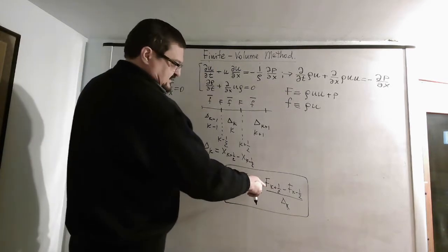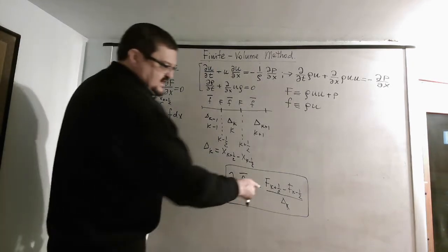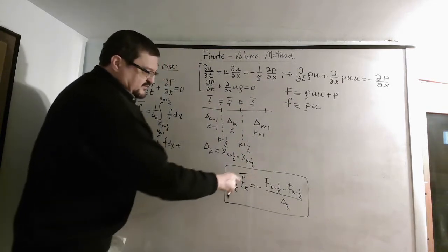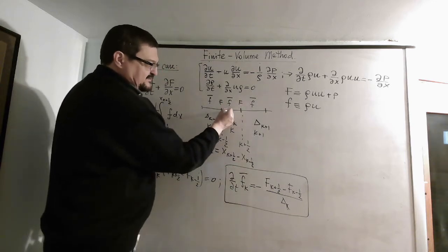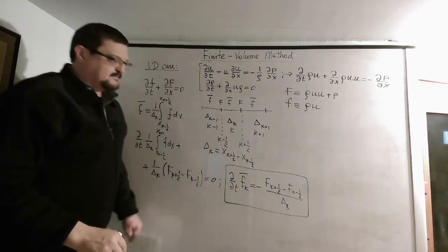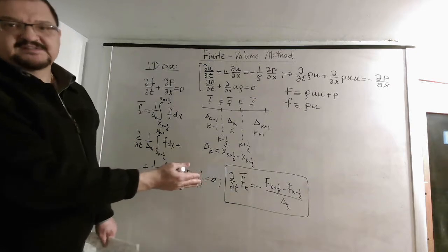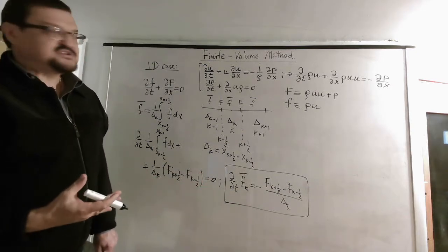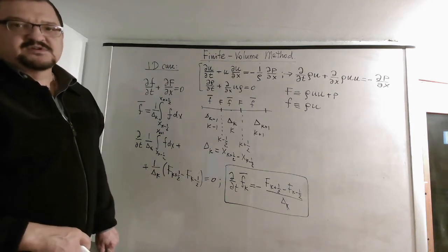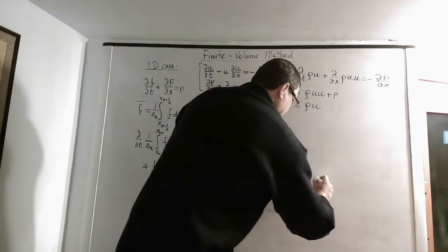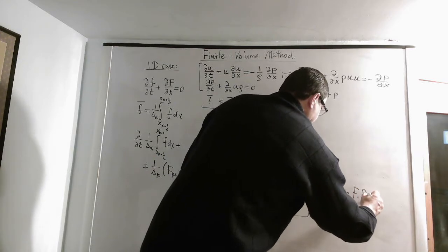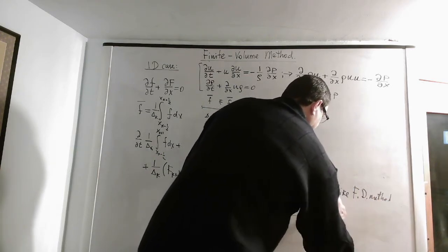So this is flux, like we did in a couple of previous lectures. It's flux at this point minus flux at this point divided by distance equals the value at this point. We assume that it's just one point, but here f means that the whole cell has this value. But the conceptual equation looks exactly the same. So in one dimension, finite volume is actually the same thing as the finite difference method. The equations look very much the same, like finite difference method in flux form.